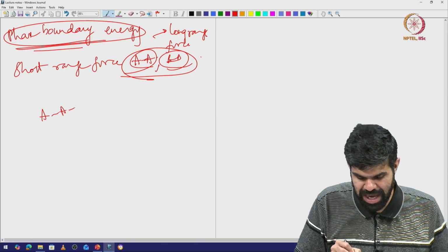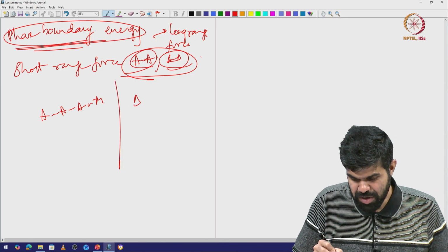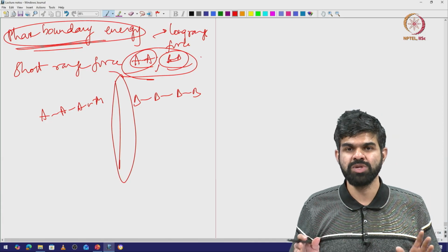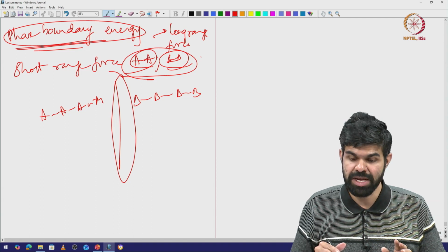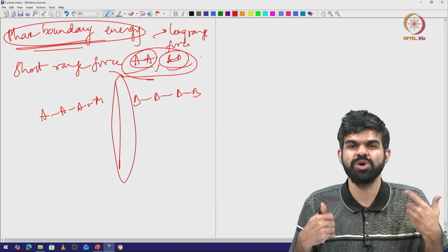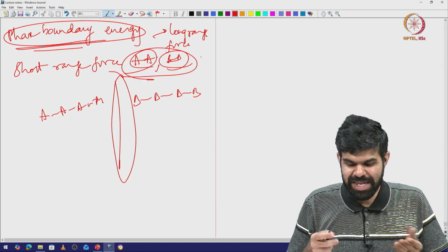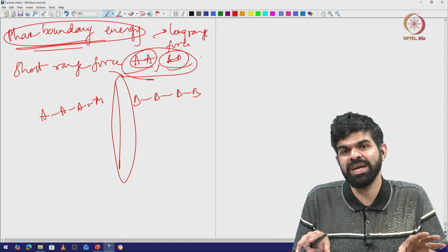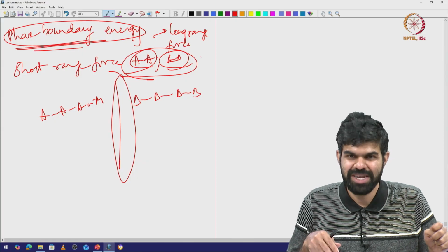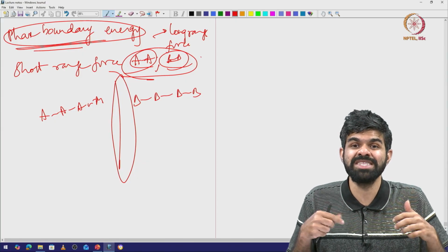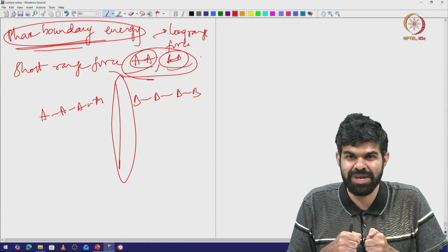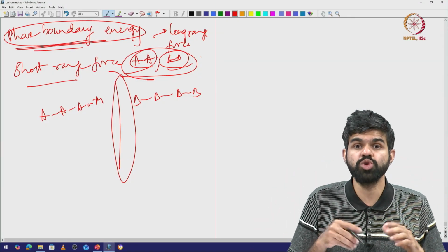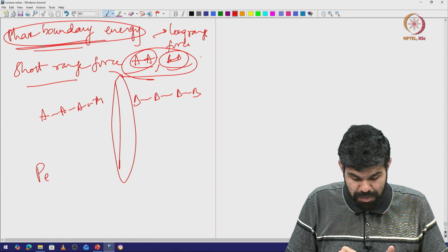So, A phase to form, but surrounding it should be the BBBB phase, and A phase is separated out from BBBB phase with a phase boundary. Phase boundary has some extra surface energy. So, I have to put in some extra energy, right, and this extra energy does not want BBBB, it ideally wants AB to be combined, so that it does not have to form this surface boundary, right. So, it is a repulsive, or in some sense it is not letting this segregation happen. So, it is like a repulsive force, right. So, in the long range. Okay. So, when those two interact, I get what are called periodic patterns, right.